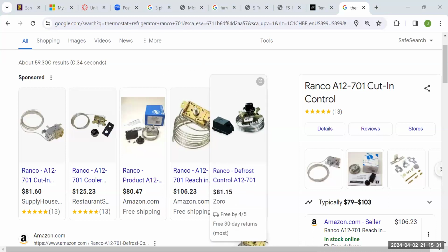Now with the sensing bulb, or with the diaphragm, we're limited on how much movement we can get off that diaphragm. That diaphragm is just a thin metal disc. So if I want the control to cover a big range, a diaphragm type control is not the best way to do it. What the manufacturer will do is they'll have a control with bellows.